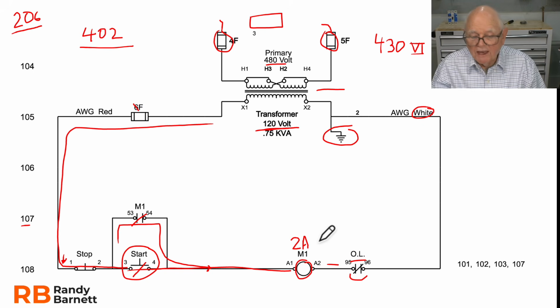the coil would draw 2 amps of current flow. Now, there were some LEDs actually in those push buttons that we took a look at, but that's going to be a pretty low value as well. So if we calculate this particular circuit, we're certainly going to be a lot less than 6 amps of current flow. So according to the table in 402 on fixture wires, we could use 18 AWG right here.